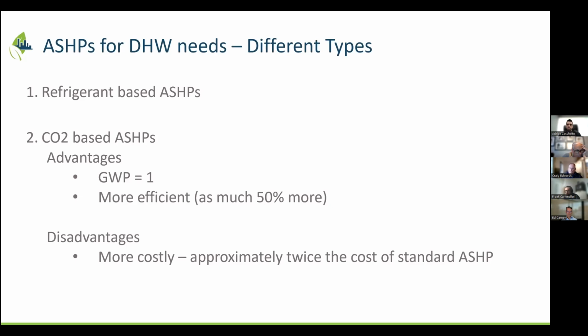The electrical service implications of these: most of these have generally been using natural gas as the fuel source. What's your observation in terms of the implications on the electrical side for these units? Yeah, well, if you are replacing gas, obviously you're changing fuels over to electric, and having electric backup as well as your compressor, the two things are definitely going to be a higher electrical disconnect than you had with your gas heating appliance. So that's something to keep in mind. But depending on the type of facility, you should have sufficient power, and usually it's just local. What I mean by local is in the area that you're using it may need the power upgraded, but it generally doesn't affect the feed into the building or anything that dramatic.